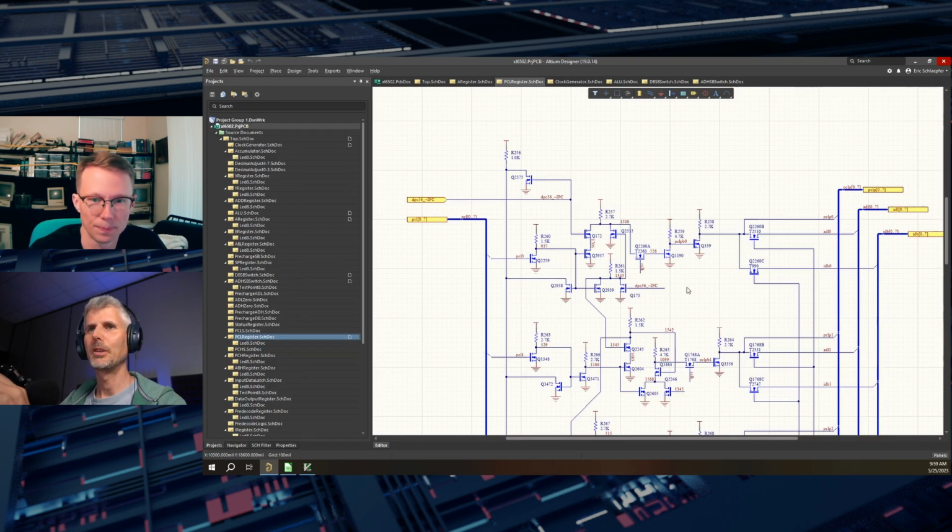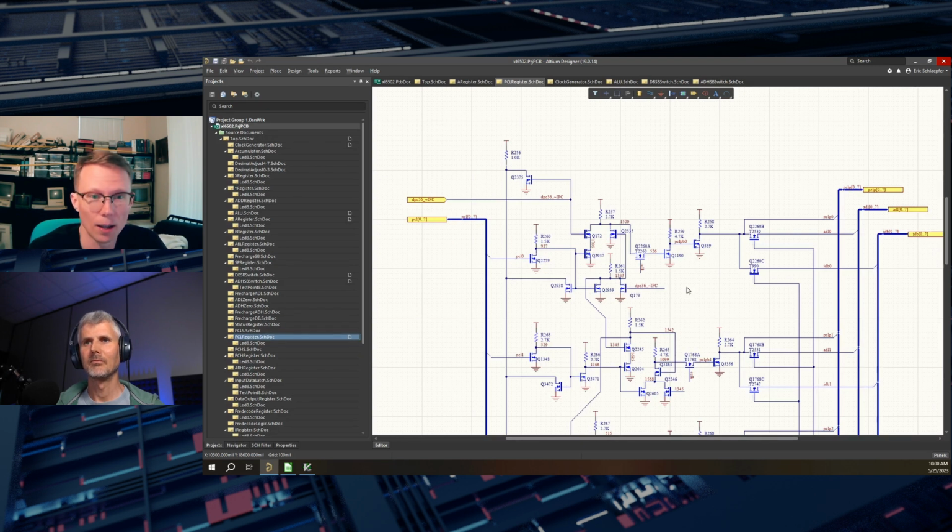So now you're recreating this at the PCB level. Right. Things might not work exactly the same, because you've got totally different types of devices and all your parasitics and everything else is all different. Yeah, exactly. I can't use a depletion mode device because they're uncommon at the board level. And so I just substituted them with resistors. Same kind of story as the transmission gate. Yes, exactly. But luckily you had a bit of an easier workaround there.